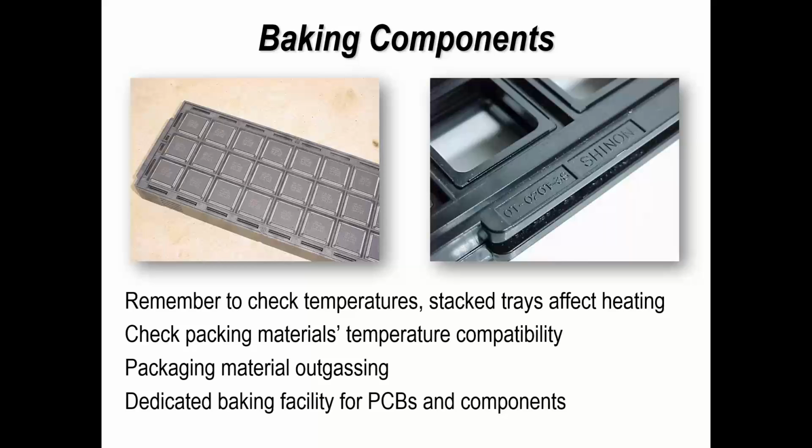There are restrictions, because you can't bake components that are tape and reeled. If you've got large components that are tape and reeled, and you bake them, you will affect the peel characteristic of the cover tape on the package, and you may well damage them. So again, that's something you need to consider.